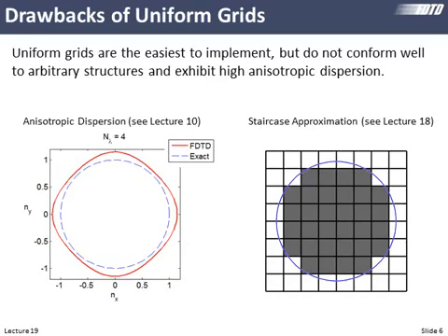Then we talked about our Cartesian grid. We have a very uniform Cartesian grid, very easy to work with. However, it has some drawbacks, and it turns out a wave propagating through a Cartesian Yee grid actually travels slightly slower than a physical wave would. And in fact, that speed difference changes depending what direction it's traveling. And so it has an anisotropic dispersion, if you will.